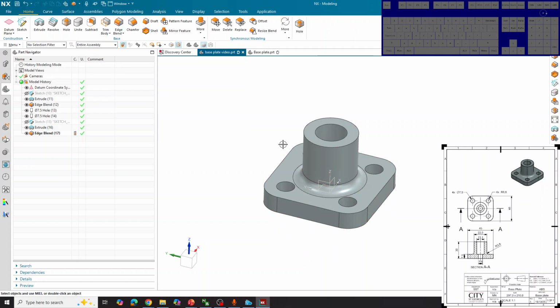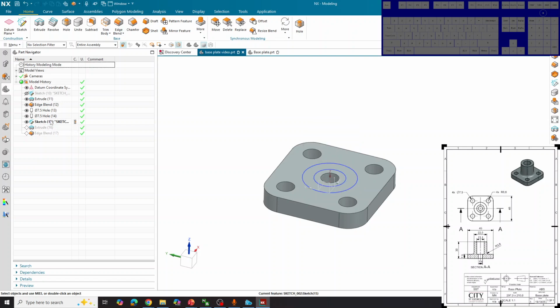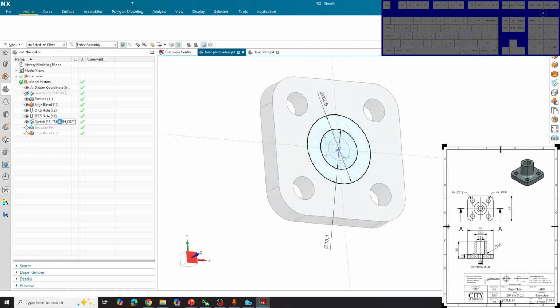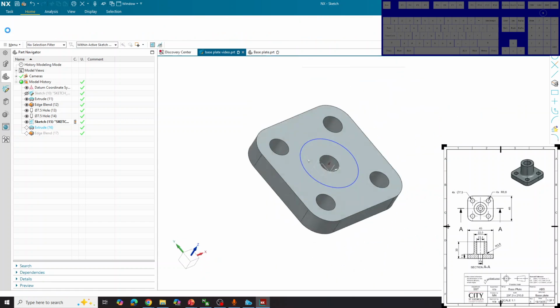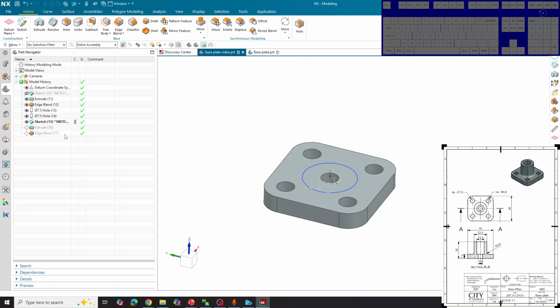Another alternative way of making this cylinder bit over here, so we can press on roll back over here. So click here to kind of go back in time. Show the sketch, yeah. And what I'm going to do is I'm going to edit the sketch and I'm going to delete the smaller circle. Okay, so what this will do is it will just extrude this massive circle over here, like so. So if I click over here, it will reveal the extrude tool, okay, like so.